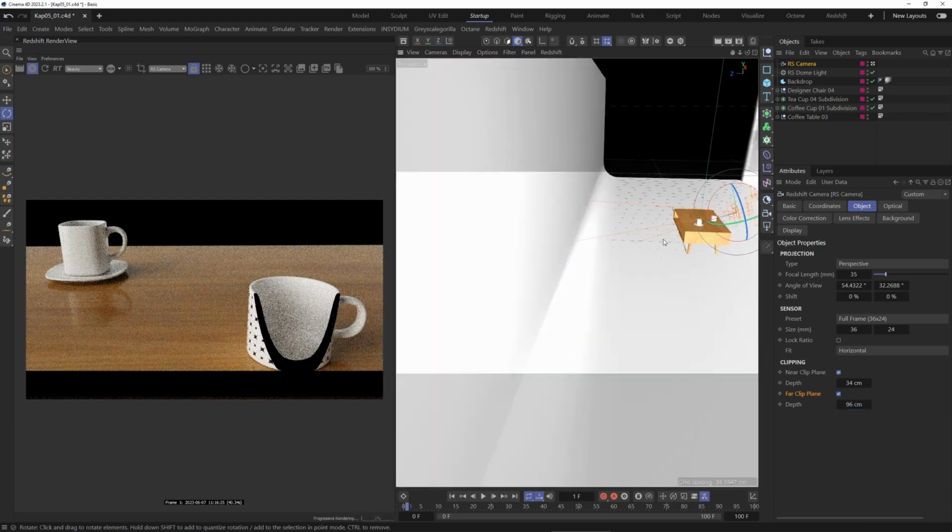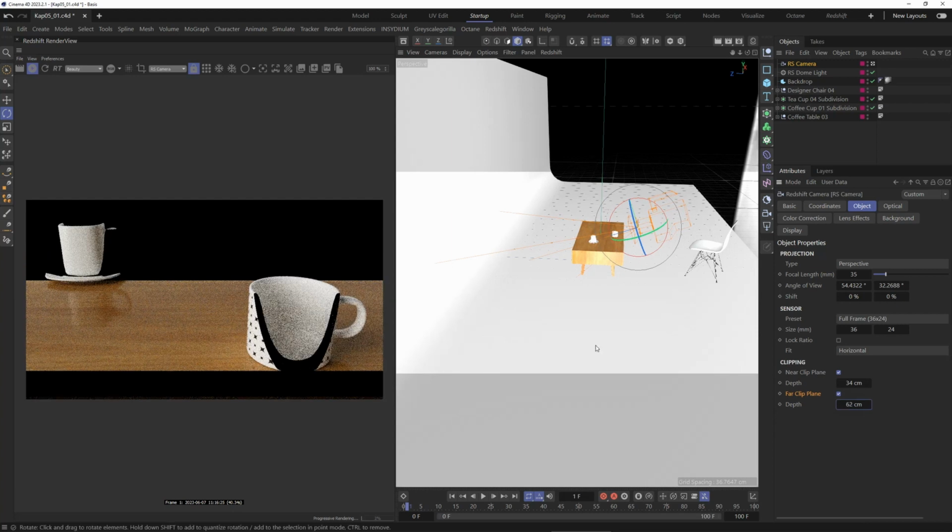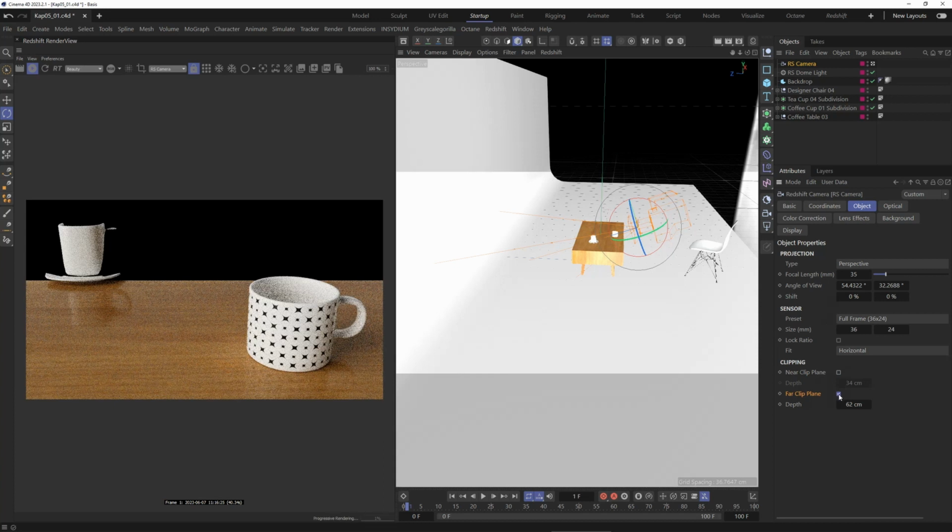I will drag it a little further. Now we are at the table and approaching the cup. We can also influence up to which point the camera considers the geometry. These were the parameters in the object area for now. I reset everything and disable it here.